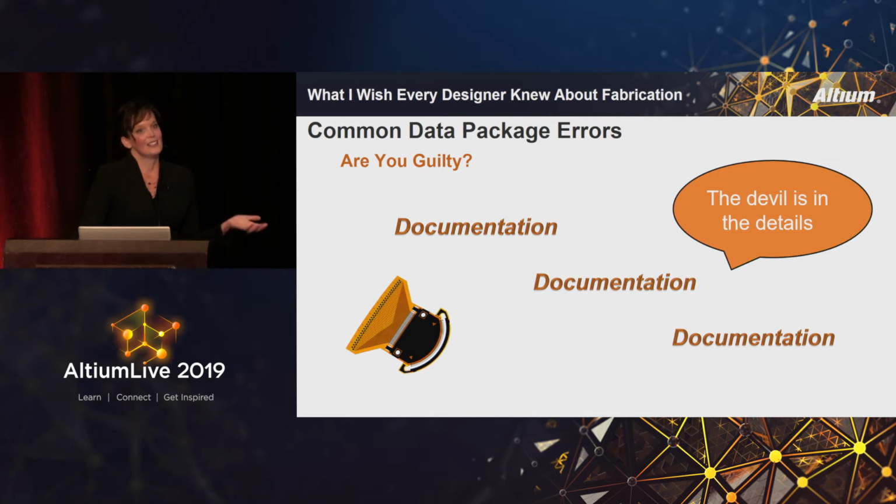The first thing that came up was the data packages, right? Honestly, I think 95% or even more of new part numbers go on hold when they go into engineering. But 60 to 65% of those are just from simple data package issues. So it can be the most complex design or something very simple, and it throws it on hold. They're cautioning me to please look at the data packages before submitting, making sure all the files are there, the drill files, the circuit files, the net list, the fab drawing, and that the rev levels match.